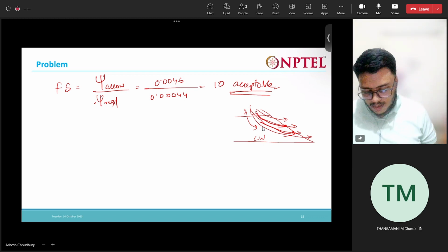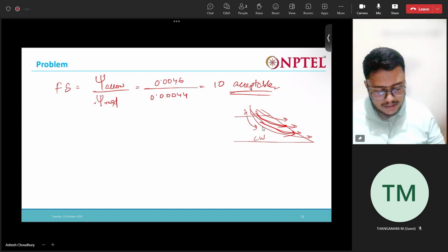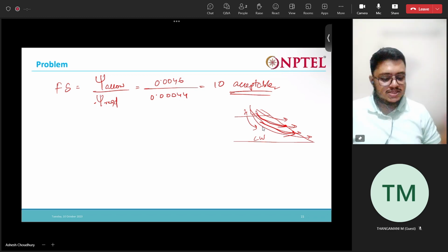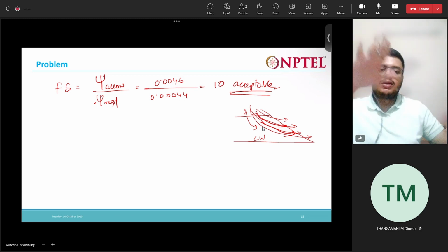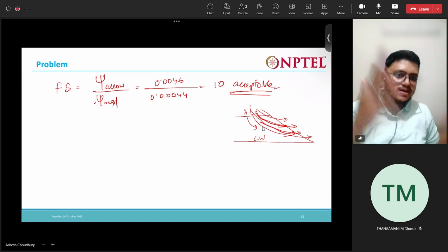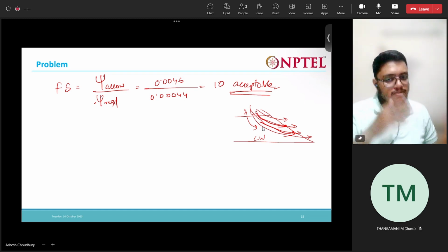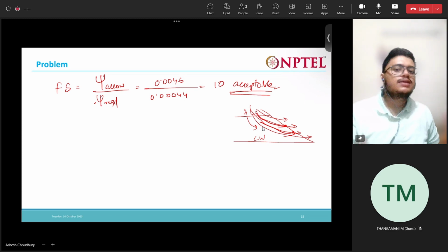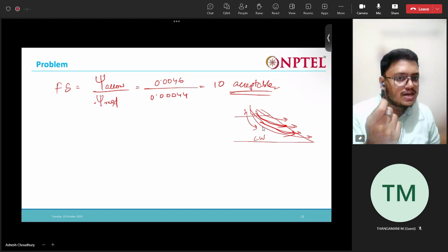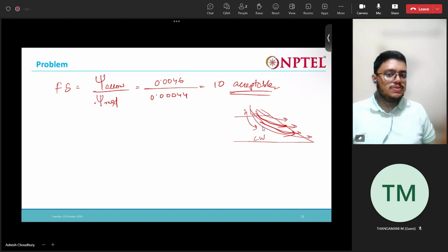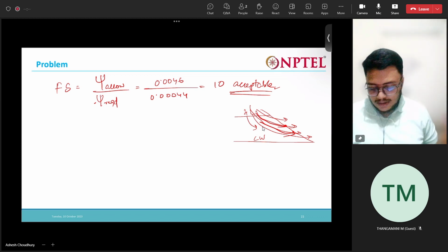Okay. Now next, after the flow criteria, is the retention criteria. We found out that it is allowing whatever flow of water is generated due to the lowering of water in the tides. Now we have to check whether the geotextile is preventing the soil particles of the beach sand, whether it is arresting the passage of those soil particles or not. Okay, that we need to check.